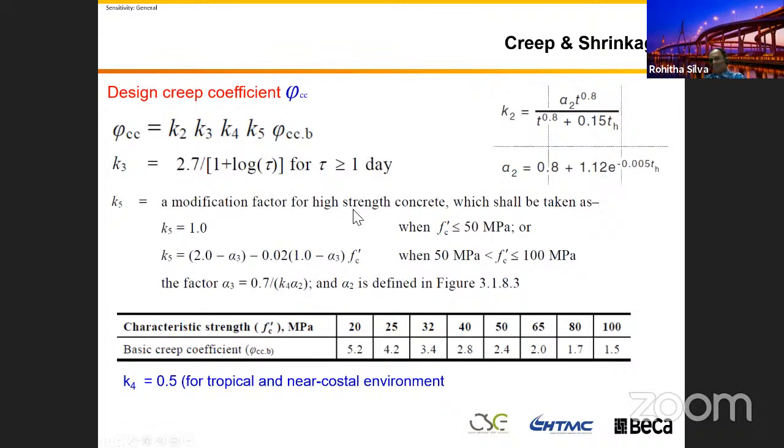I'm not going to discuss the creep behavior, the secondary creep effect, and those things when you apply load and when you remove it, like in certain bridge construction, for example balanced cantilever. If you are interested, if you are doing a problem, if you have any specific questions, we can discuss. And all these parameters define this important parameter, which you can see is time dependent.